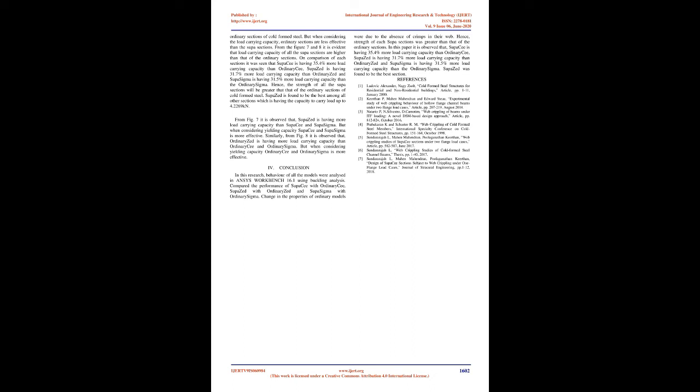Table 2. Maximum deformation and force reaction of all sections. Section, max deformation in mm, force reaction in kN. Supa C: 67.629, 2.849. Supa Z: 46.71, 4.2269. Supa sigma: 64.541, 3.1266. Ordinary C: 49.59, 2.1042. Ordinary Z: 26.86, 3.2086. Ordinary sigma: 41.764, 2.3765.